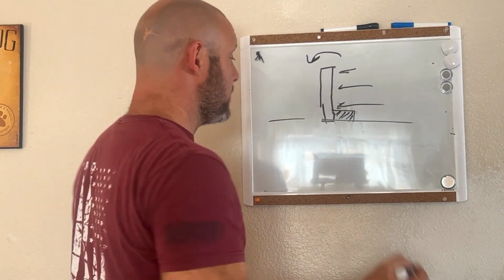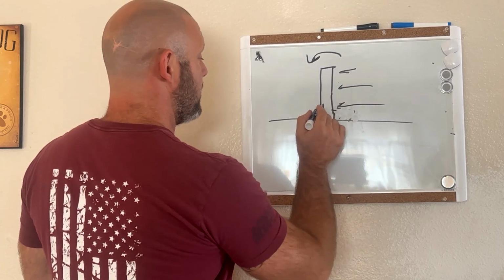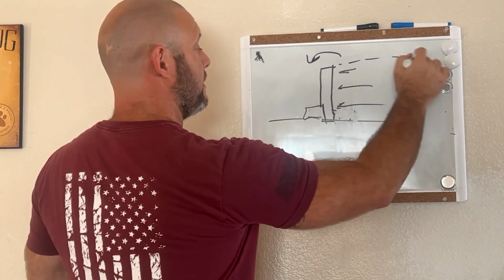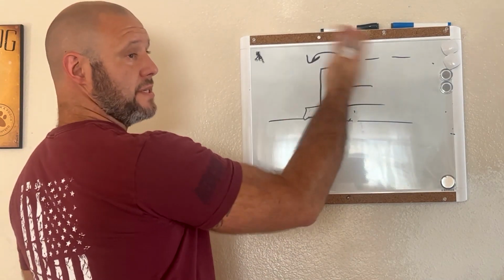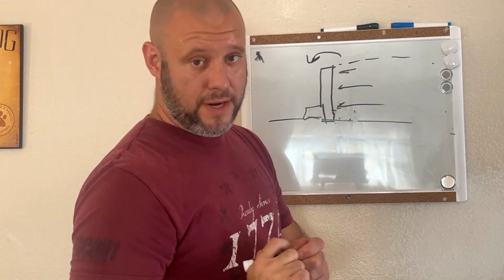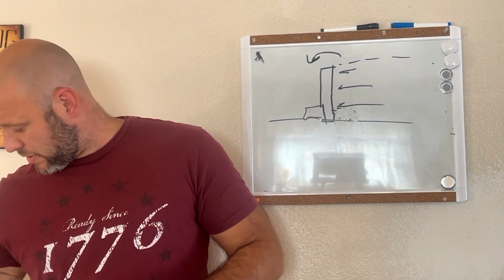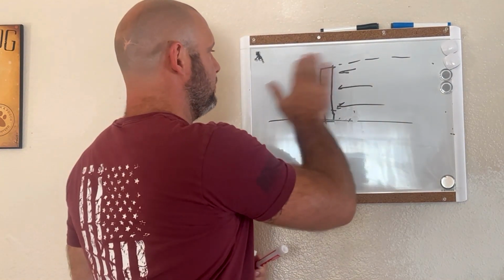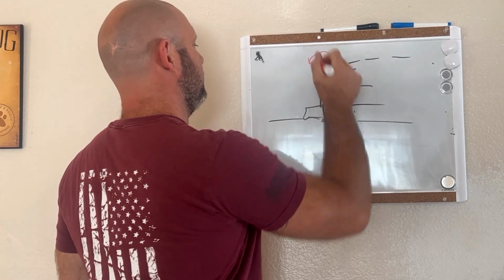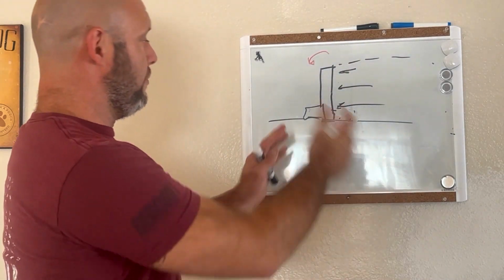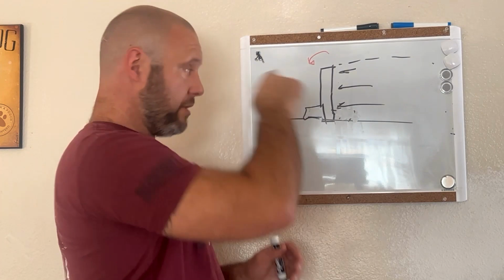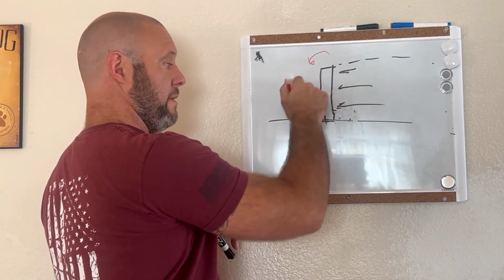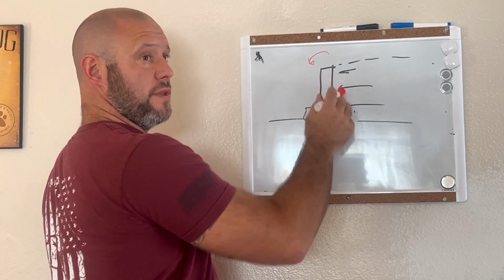So at first glance, you would think the better support would be an L shape away from the hillside, because it would resist that overturning moment. But I should grab a couple different colors just to help out. And it will resist that overturning force. You can imagine you apply pressure up top. This resists that overturning motion by resisting the downward force here, and that works.